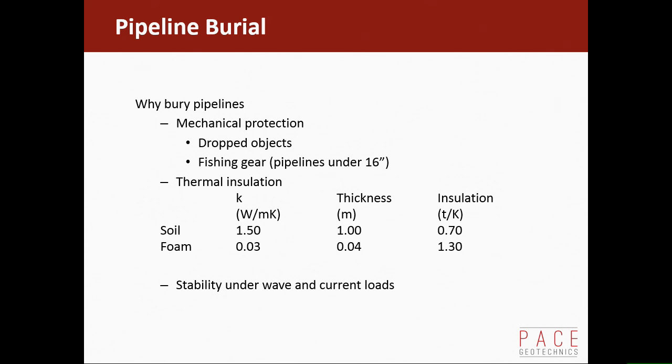It is expensive to apply, and because it's quite thick in reality, it's reducing your capacity or the length of pipe you can get on a reel lay vessel, because you've got a drum size there, which you may be okay, but if it goes over a certain value, then you've got another trip to port to pick up more pipe and pick up the end of the pipeline, connect it, lay away again. So you get a benefit from it.